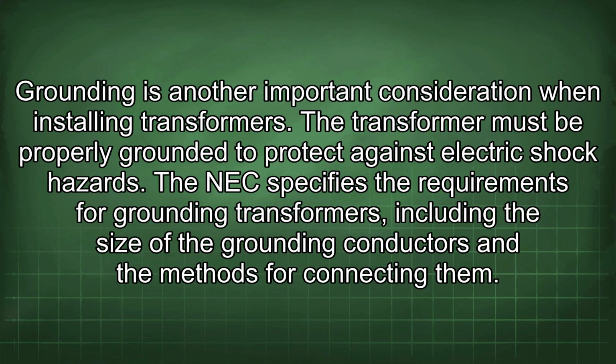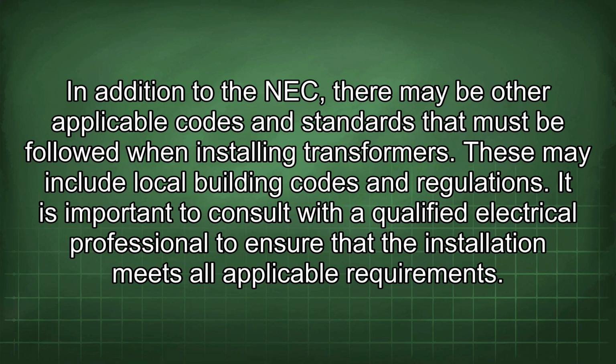Grounding is another important consideration when installing transformers. The transformer must be properly grounded to protect against electric shock hazards. The NEC specifies the requirements for grounding transformers, including the size of the grounding conductors and the methods for connecting them. In addition to the NEC, there may be other applicable codes and standards that must be followed when installing transformers. These may include local building codes and regulations. It is important to consult with a qualified electrical professional to ensure that the installation meets all applicable requirements.